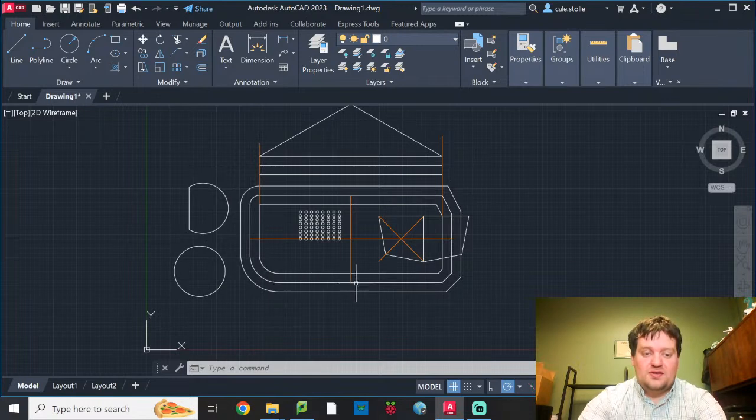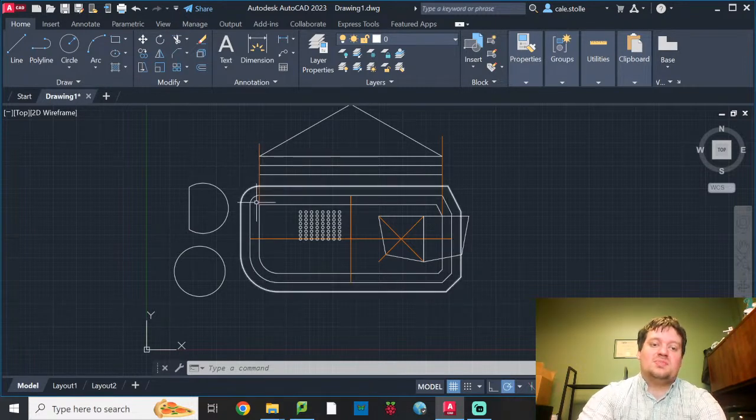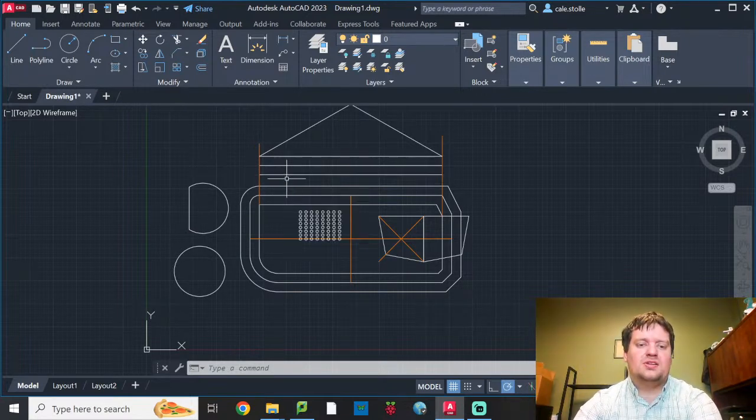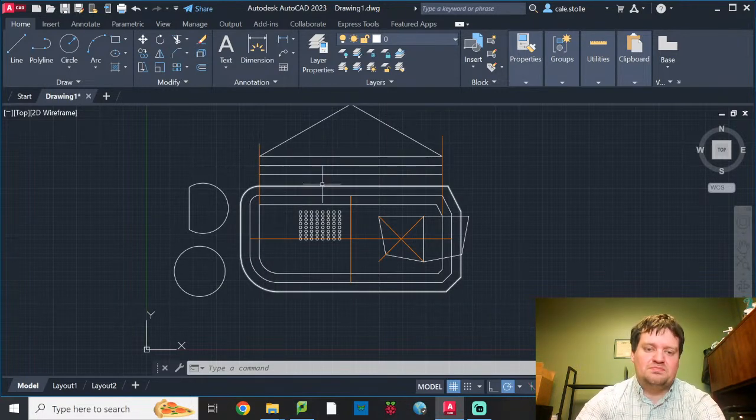Okay, you have to show me that you understand how to do it with polyline by having it show up like this. If you didn't do it as a polyline, the lines will have to do intersections. You'd actually have to go in and do a bunch of trimming to try to make it look like this and this. It's a big waste of time, if you ask me. It's just easier to do as a polyline. You then have to come up with one line here, and then you will need to offset it twice again.